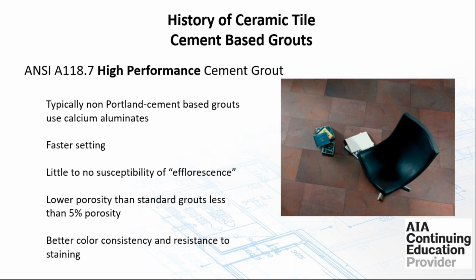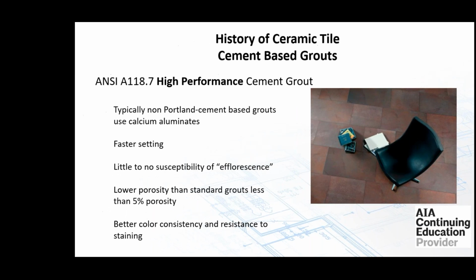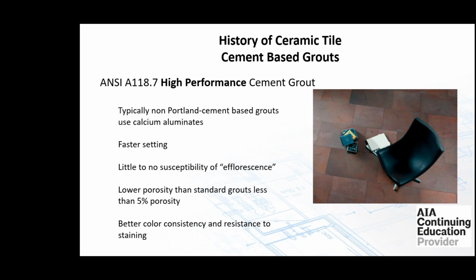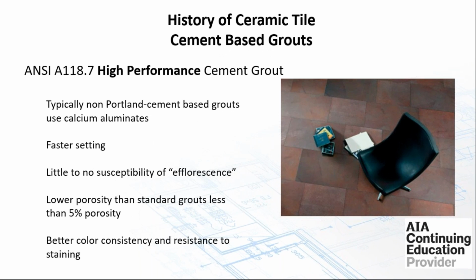It has a lot lower porosity than a standard grout, typically less than 5%, and consequently better color consistency and resistance to staining. With this type of grout, if 3 of us are in that same room again and I'm working in the corner, and somebody's under the bright sun in the window, and somebody's working by the open door, the consistency of the color will be pretty much the same across the floor.